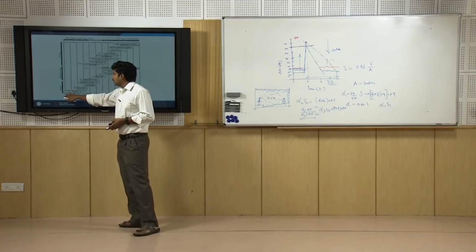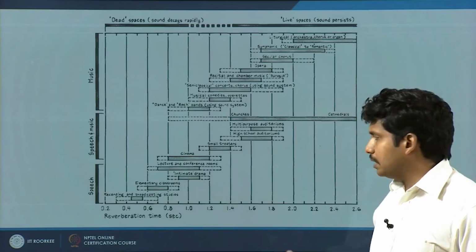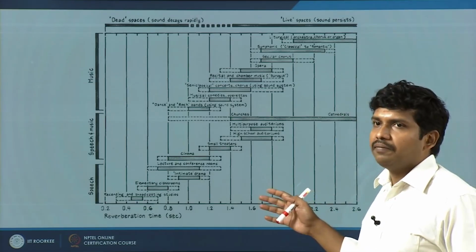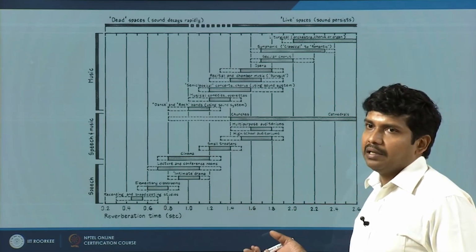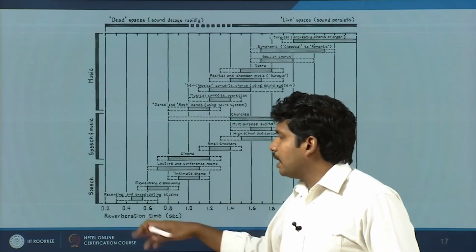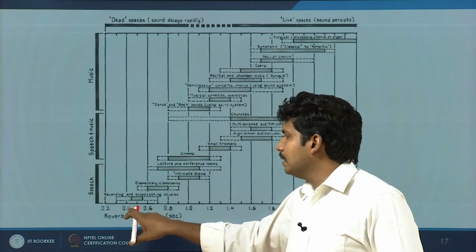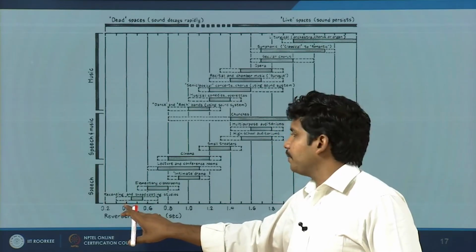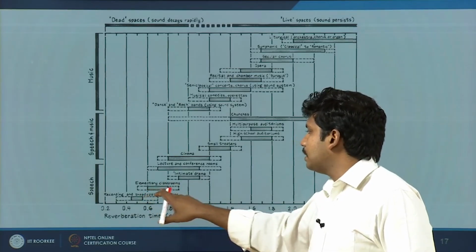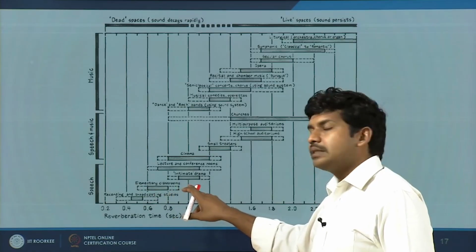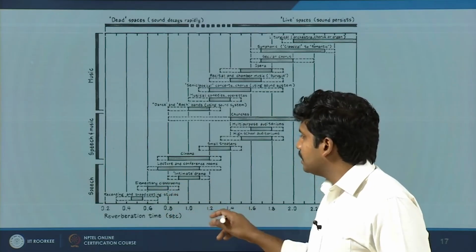If you look at one end, a recording or broadcasting studio, a small recording theatre kind of space, most commonly found in radio stations and typically TV or radio broadcasting stations. They are highly absorptive, typically small rooms where a reverberation time as low as 0.4, 0.3 is expected. Typically classrooms, you can expect, as I said, somewhere between 0.5, 0.6, it can go to 0.8, 0.9, sometimes you will find 1 second, it is not bad, somewhere around 0.8 is advisable.